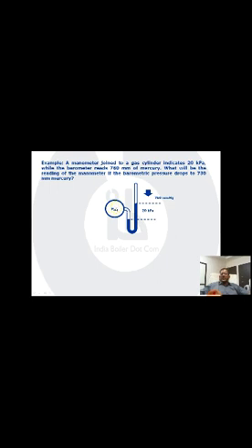what is going to change in this case? So if the barometric pressure changes and the absolute pressure doesn't change, what is going to change is this differential reading, right? So we know the manometric differential reading is what? It is P absolute minus 760 millimeter of Hg. That is 20 kPa that has been given, right? So P absolute minus 760 mm of Hg is 20 kPa.